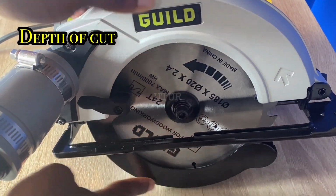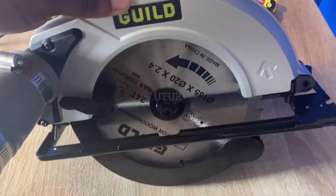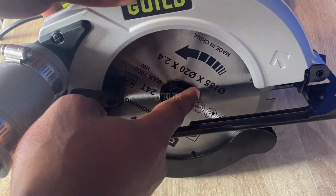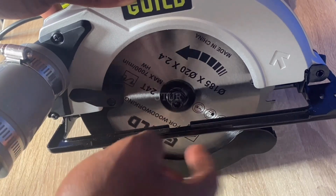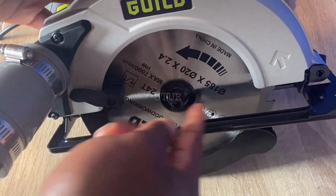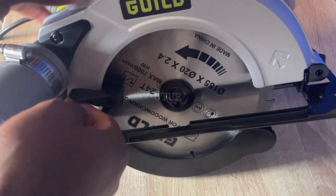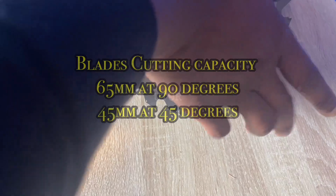And for the depth of cut, if we lift the lower guard lever to reveal the lower blade guard, it reveals the blade, and when we visually inspect the blade, we can see that the blade is too far out from the base plate. And that's because we do not need all of that blade protruding from the base plate if we're just cutting a hardwood plywood of about 12mm.